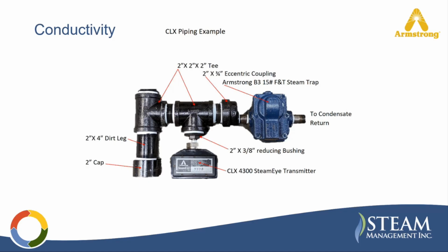If condensate begins accumulating upstream, it can indicate a drainage problem, a failed trap, excessive back pressure, or any other type of system issue. And for process equipment, this backup can reduce efficiency, lower production rates, and negatively impact overall operations.